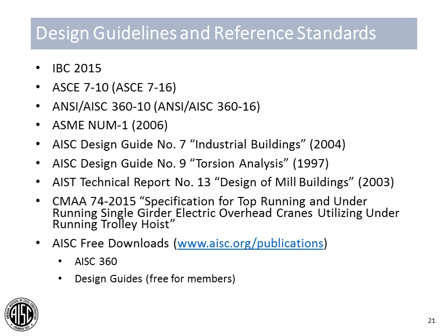There are a number of different design guidelines and standards that are utilized. There's no specific code that specifies the design of these underhung crane systems. IBC and AISC E7 do provide impact factors for crane loads, but they're very vague, and AISC E7 actually does not even include load combinations for crane loading. The AISC 360 specification, that obviously will be utilized to develop your allowable strength criteria for your runway members, and also the fatigue considerations that we'll discuss shortly.